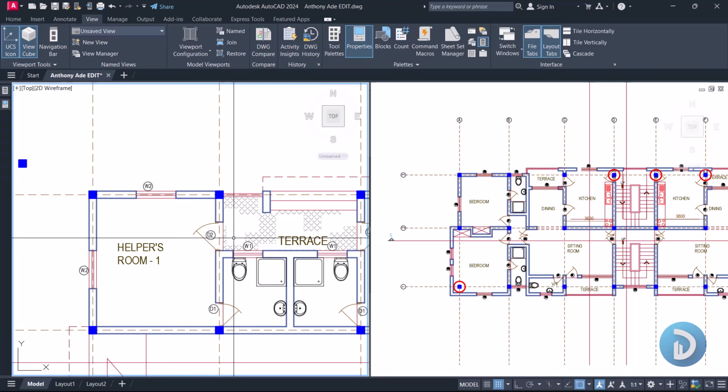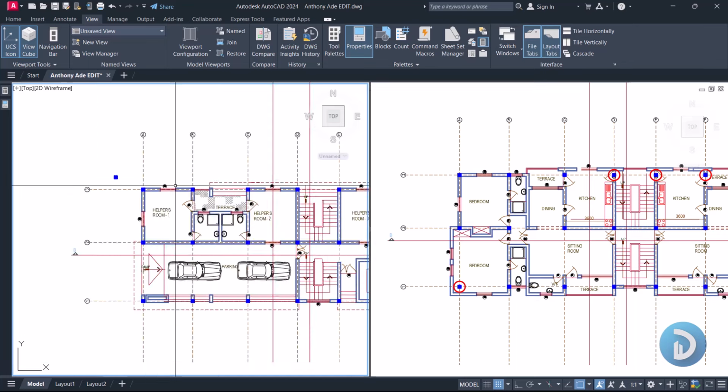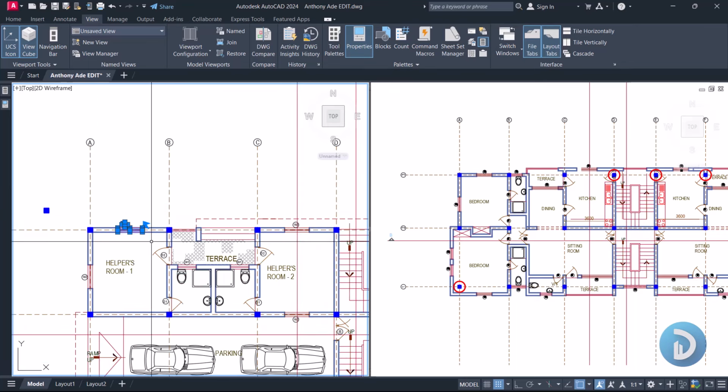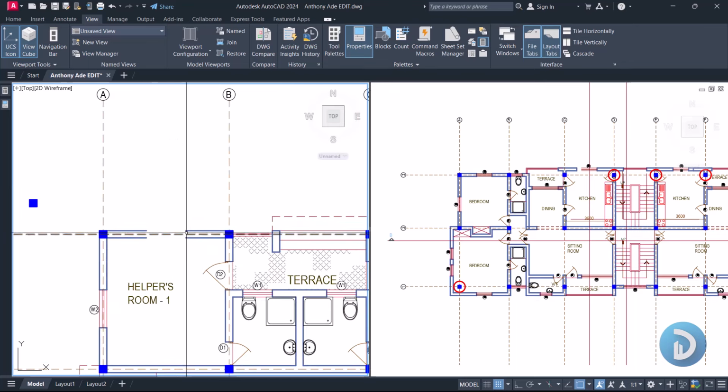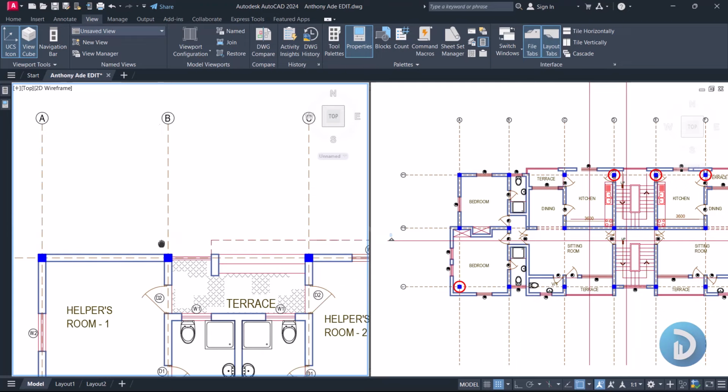Now we'll be running our beam structural arrangement on the existing column, starting from the ground floor. So we'll try our possible best to ensure our beams run on the wall lines, except where necessary. And this is to allow us cover these beams by the walls that will be constructed on site. So we'll start off moving from grid to grid. So we can run a beam from this column to this column. We can run a beam here.